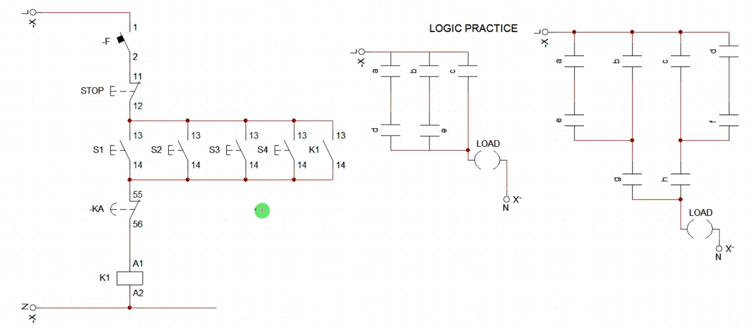Now, this is a latching logic. From here to here and here is called latching logic. Use this one to latch this motor. By pressing any of these, it can latch and continue the same operation. All right. Now, how do we shut down the operation? Because the stop button is very far from these locations, we can only activate, and the system gets deactivated automatically. So how do we do that?